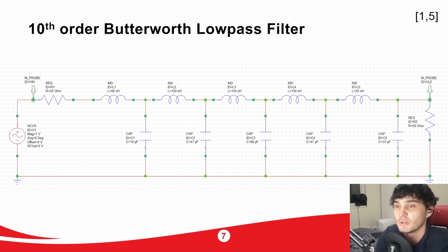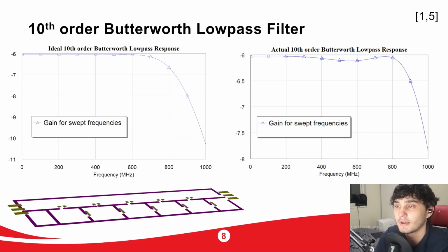I designed and simulated a 10th order Butterworth low pass PCB. I simulated the components using actual surface mount device, high Q, inductor and capacitor values that I have. Here I showcase the filter's idealized response and the actual response based on the values that I have.